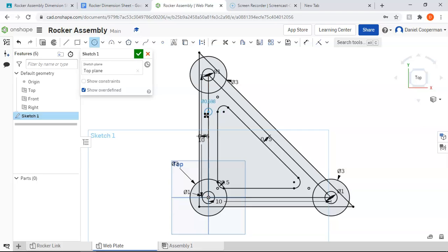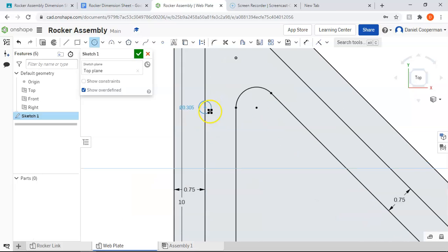line right here. And one thing you want to be very mindful of is when you create this circle, once you click the first time, you then specify the diameter. You want to be careful where you click. If you click where it gives you an auto suggest, see how it jumps right there? If you click there, you are essentially creating a connection between this circle and that point right there. But you don't actually want them to be connected.